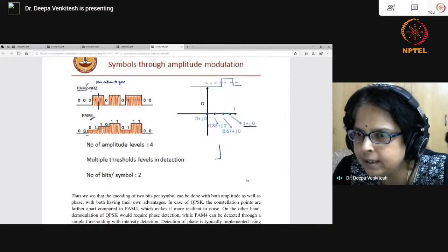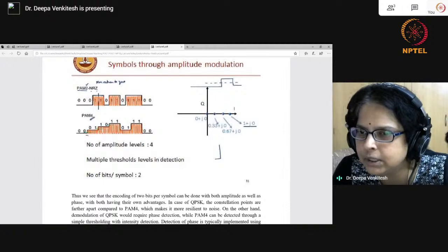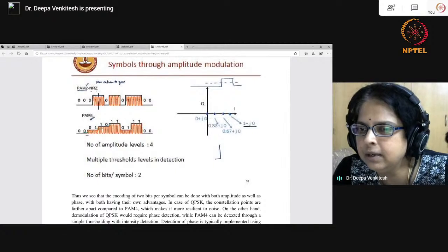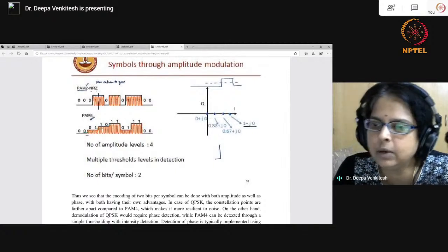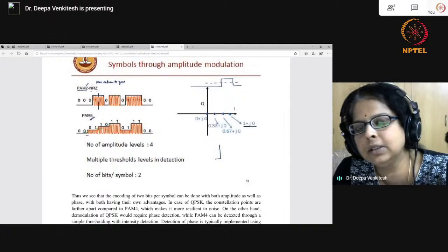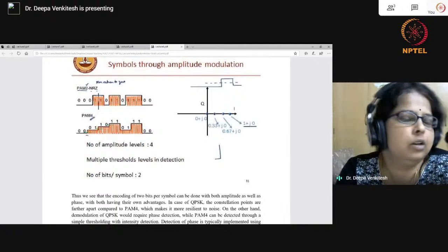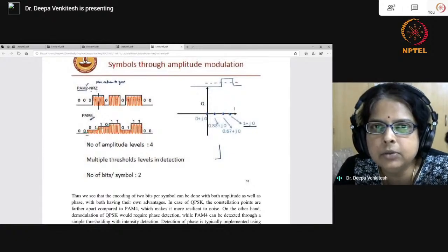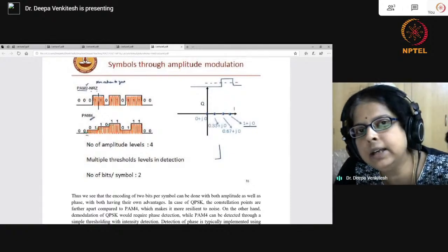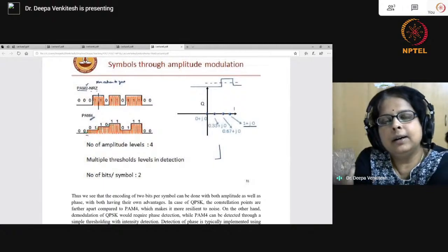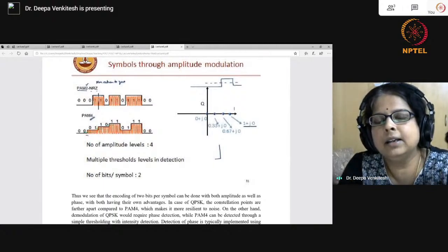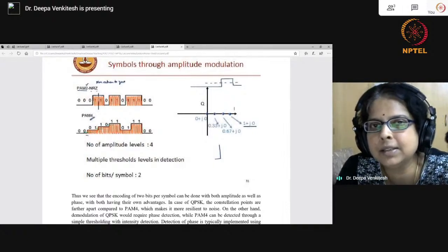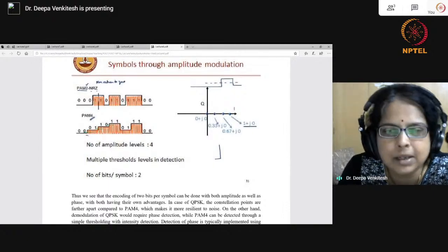Michael's question is again: you mentioned NRZ is used in the current system, which requires a clock signal as well. Why can't we use RZ, though the bandwidth required is double that of NRZ? Initially there was a lot of discussion in the industry about whether to use RZ or NRZ. It turns out that even though the clock is very easily discernible in RZ, people prefer NRZ because clock recovery is actually not a complicated task.